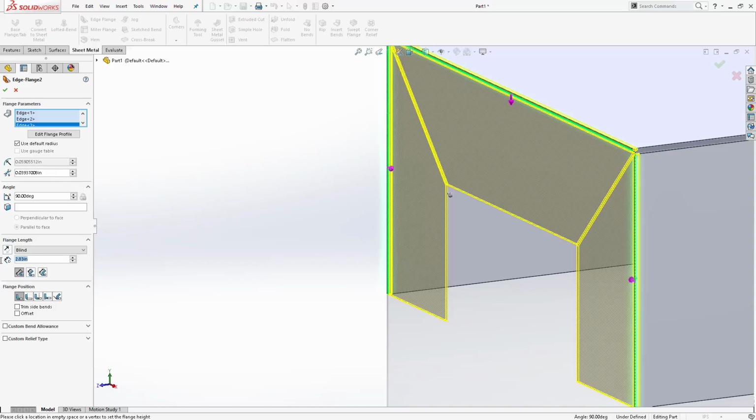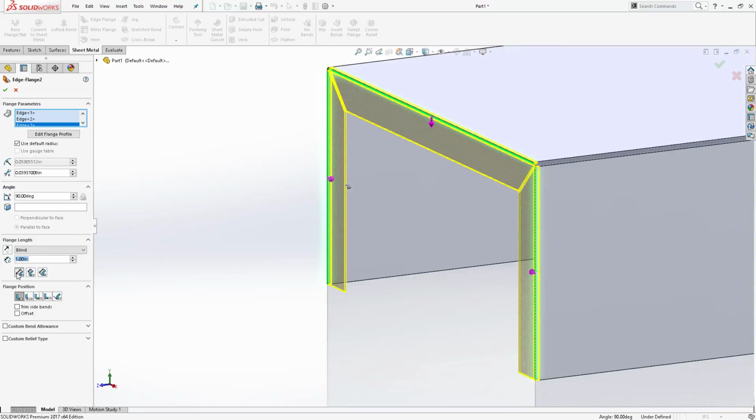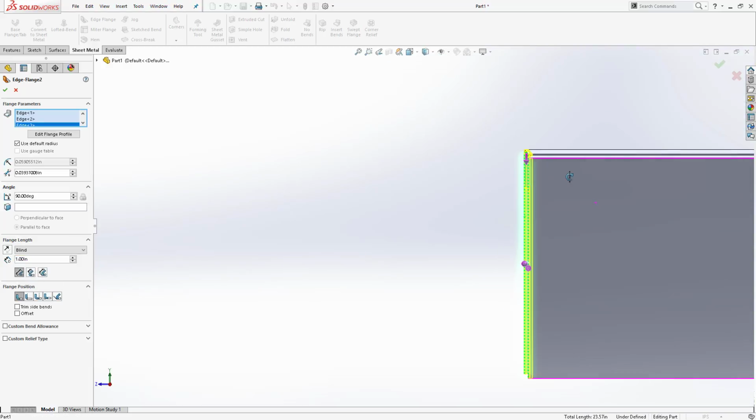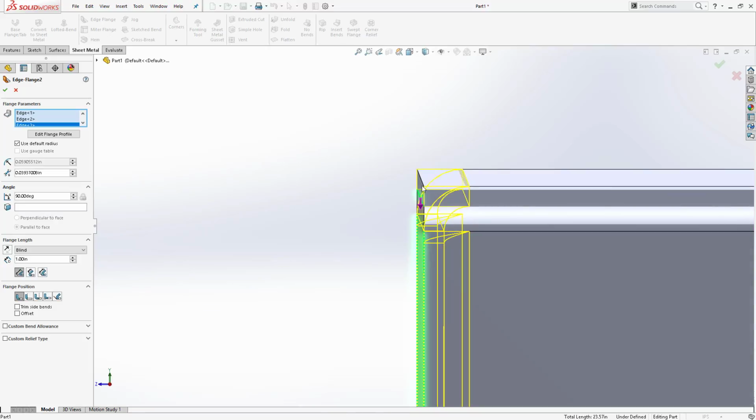Further down here though, I'm just gonna set this to 1 inch. You've got a lot of different choices for where you actually want to start that flange length from. So that outer virtual sharp is basically, if you imagine where the corner of this material is. It's going to change as that angle changes, right? So kind of where the material would meet, where this face and this face intersect. So virtual sharp can change.